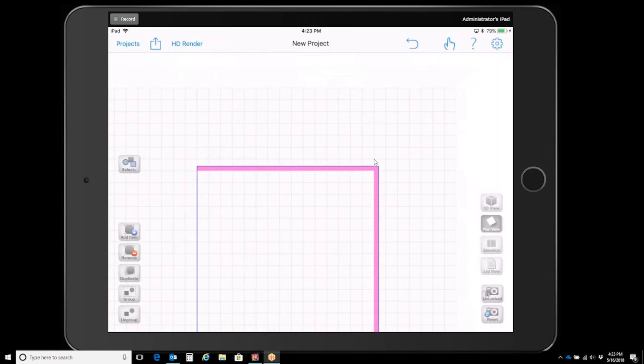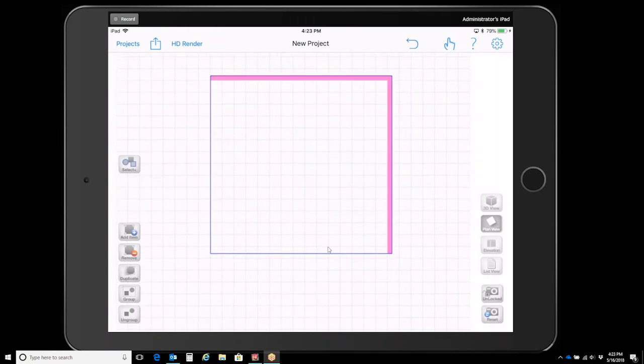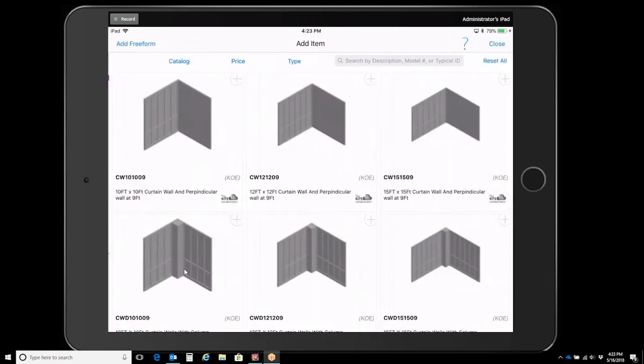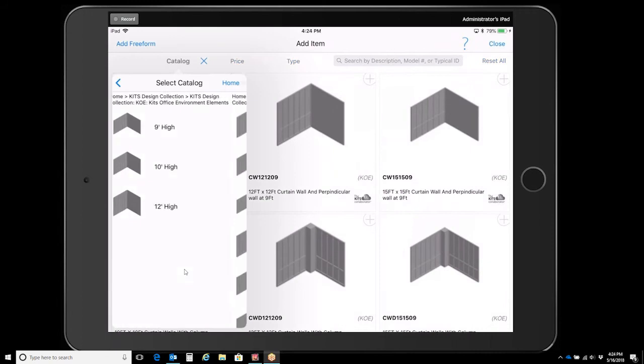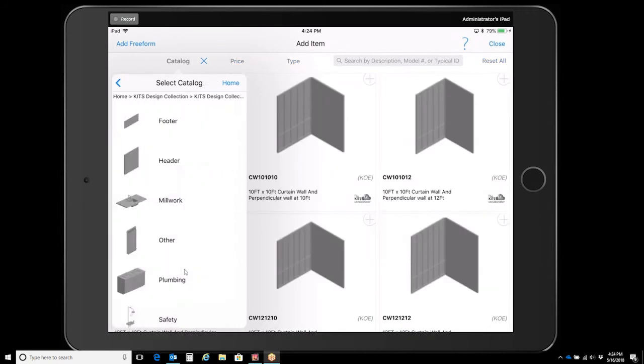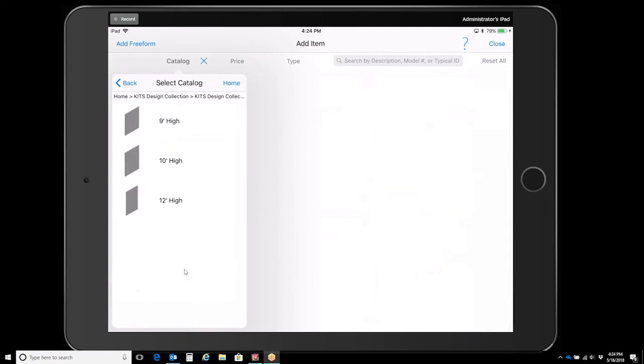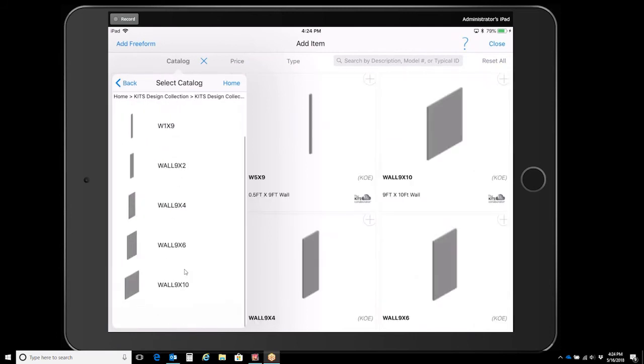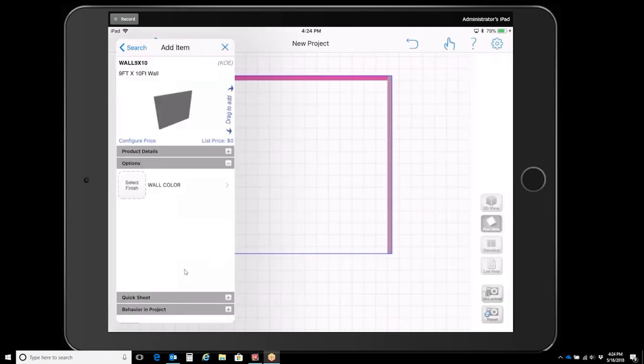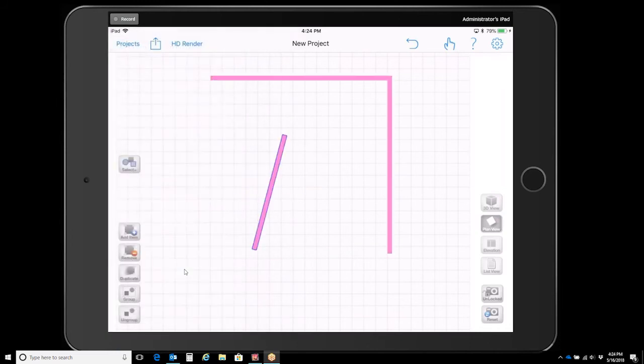And I just double tapped on the image, and now I'm going to drag it into the space. I'm going to go into plan view. I want to make sure that I'm utilizing the floor grid properly, and I'm going to place the items in the center of the floor grid. And then what I like to do is, with these wall typicals or layouts, I like to place the floor grid square on the inside so that now I know that I'm using a 15-foot by 15-foot length.